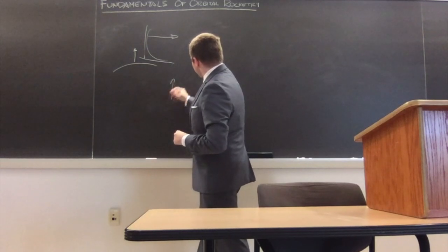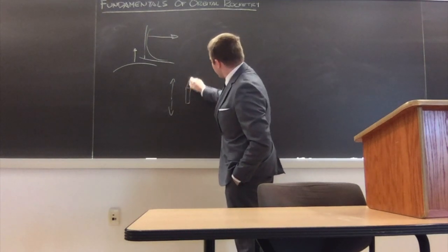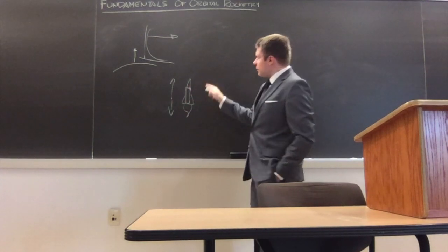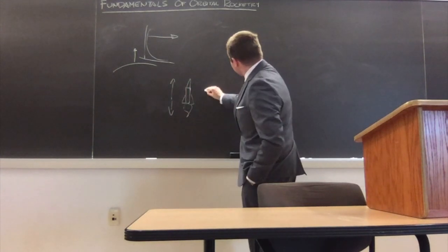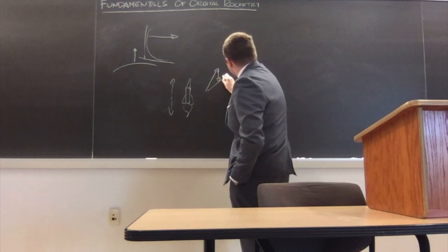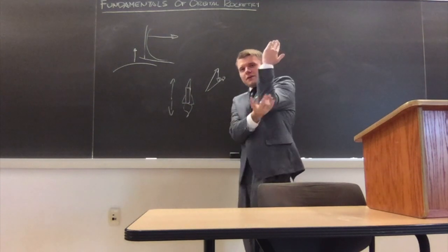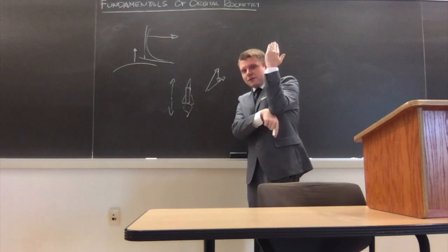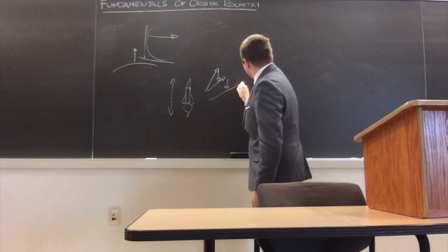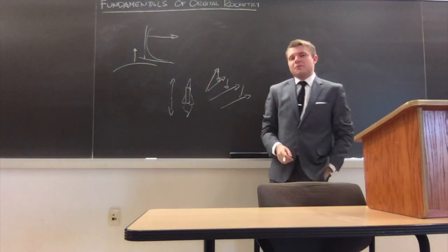When you're going upward, your gravity losses are pointing this way. Your velocity vector is this way. The rocket is, of course, pointing vertical. But when you turn over a little bit, only by a couple degrees, suddenly you have this vector added on to the end, and the resultant velocity is angled as you pitch the rocket over. Because now the vector from gravity is doing this. You're doing the sum of those two. And this happens again and again. And so basically the effect is that you turn your trajectory as you go upwards.